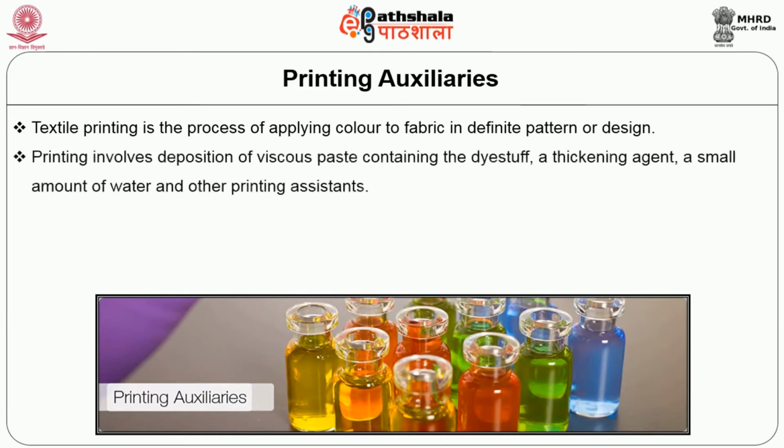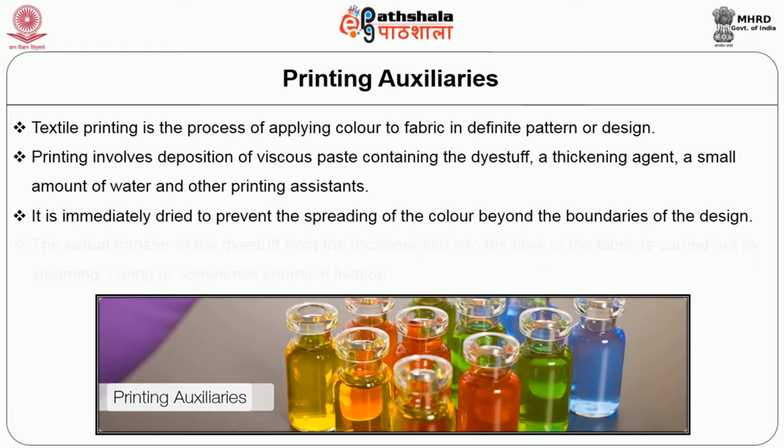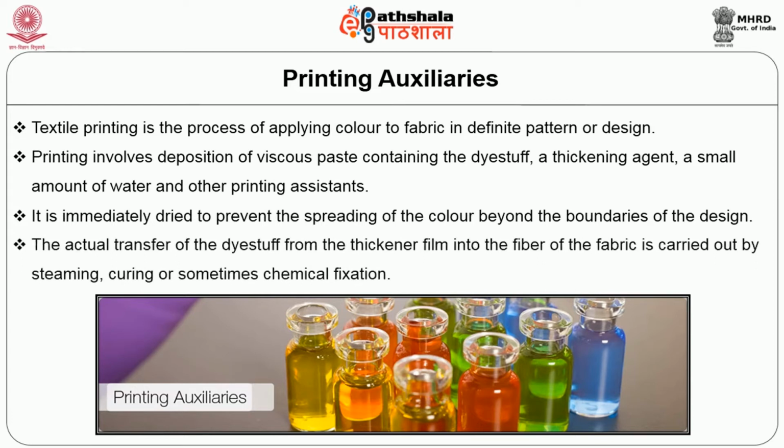Printing involves deposition of a viscous paste containing the dyestuff, a thickening agent, a small amount of water and other printing assistants. It is immediately dried to prevent the spreading of the color beyond the boundaries of the design. The actual transfer of the dyestuff from the thickener film into the fiber of the fabric is carried out by steaming, curing or sometimes chemical fixation.